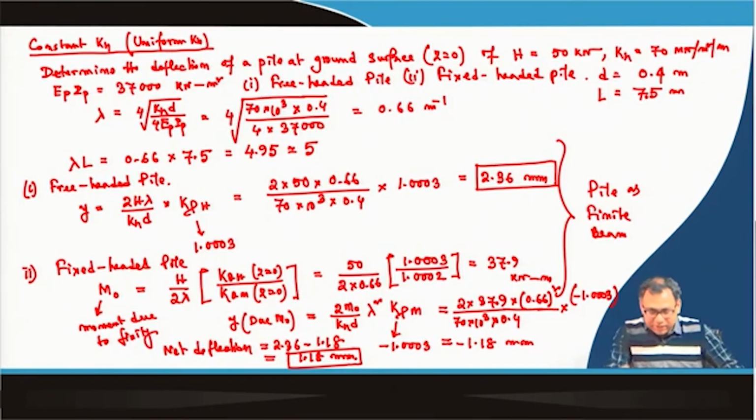But when you calculate the other coefficient, that you can calculate for the required depth, because the table is given z by L. So, that means if z equal to 1 and L equal to 7.5, it will be 1 divided by 7.5. You can determine for any depth, but this m 0 you have to determine at z equal to 0, remember that.